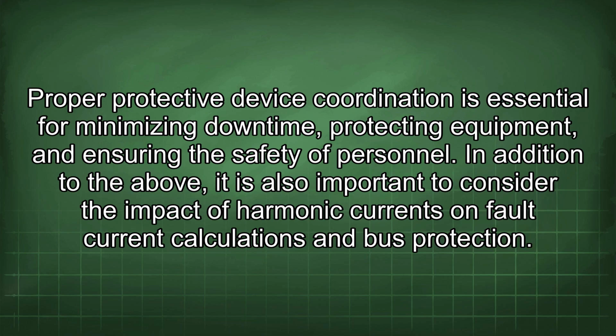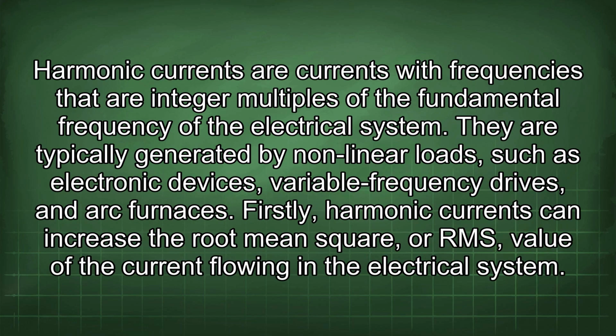In addition to the above, it is also important to consider the impact of harmonic currents on fault current calculations and bus protection. Harmonic currents are currents with frequencies that are integer multiples of the fundamental frequency of the electrical system. They are typically generated by nonlinear loads such as electronic devices, variable frequency drives, and arc furnaces.